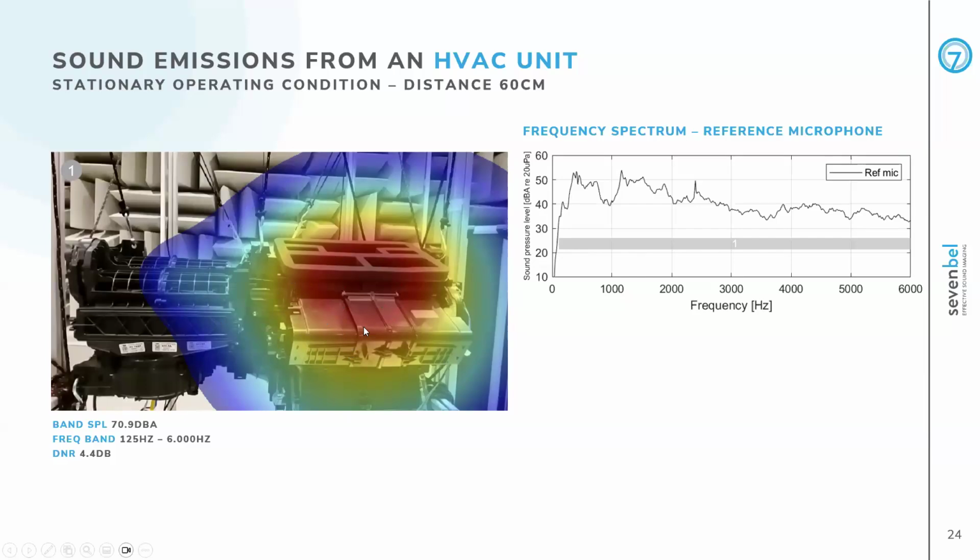We would typically now start using filters, as we did before, to separate the spectrum in different bands and understand which component is radiating which band. Unfortunately, with a complex machine like that one, this can be a pretty tedious process. There are many peaks here. We would need to place filters around each one of them, and this could take some time. But there is a faster and more efficient approach that our system will let you use.